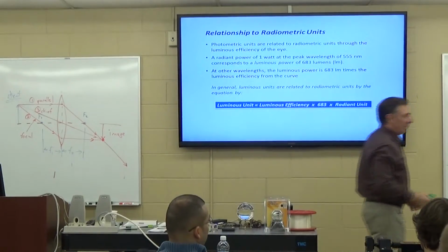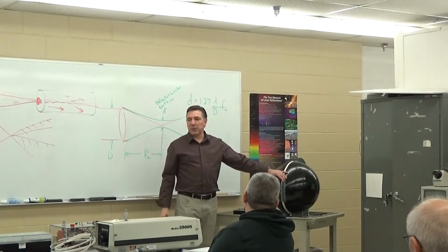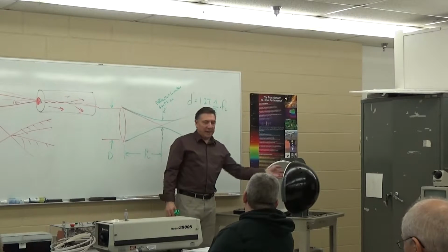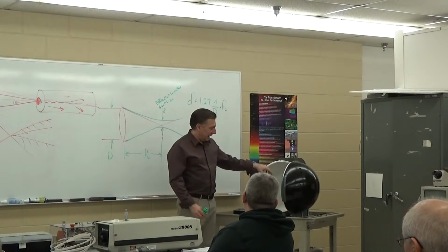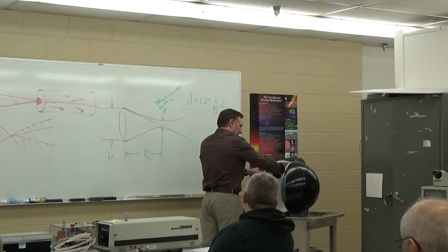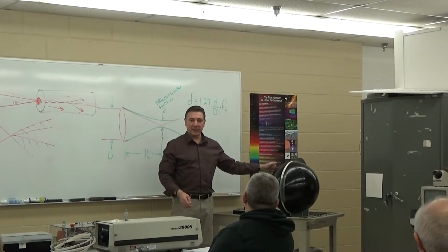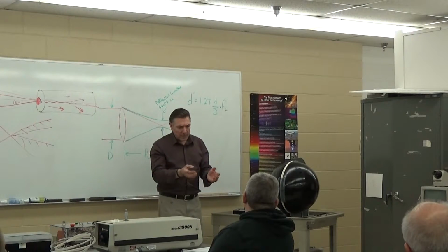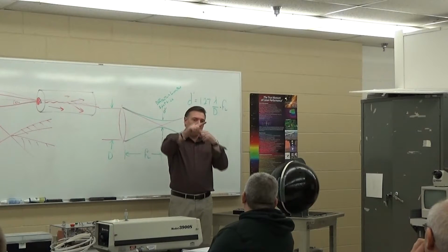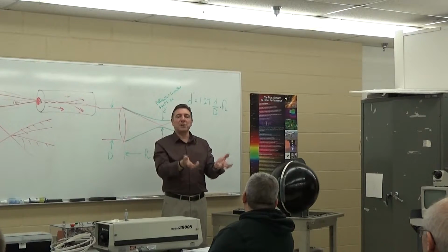I might as well show you that. This device here, which looks like the Death Star, is called an integrating sphere. Think of the word integrating sphere. It's painted pearl white on the inside. The bulb goes right in the center, so you screw it in and close this so that you capture just the light inside. When light comes out, it reflects off all of the surfaces, and because it's bouncing all over the place, it gets integrated, blended, homogenized.